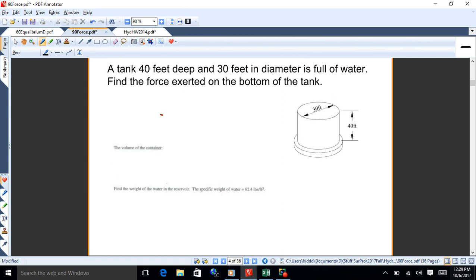So to get the volume and the weight in there, start with the area, pi r squared. For a cylinder, you take the area that you've got, and that's, of course, this circle up here, and you multiply it by the depth of the tank. That's the general formula for doing volumes: you take a constant area times the depth, which I'll show in red there. That'll get you the volume. It's the area of a circle, so it's pi r squared. Now remember, circular things we usually call out by diameter. You want to use the radius, which is half the diameter, for your pi r squared. Okay.